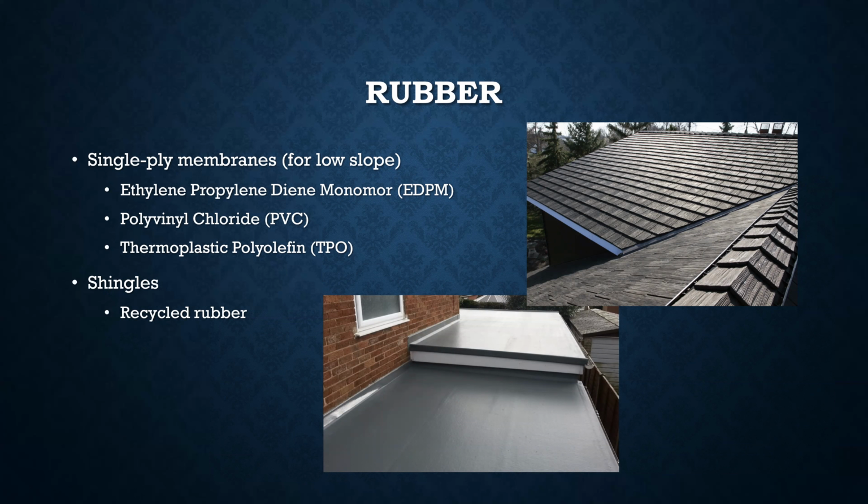There's some super cool advantages to rubber. It's a little more expensive to get on here because it is less frequently used. Therefore, labor is going to be harder to find, and the materials themselves are going to be a little more expensive, but you get to claim that you're recycling unrecyclable rubber, and they actually do stand up pretty well to abuse. The rubber material, just out of the fact that it's rubber, is going to have things bounce off a whole lot more than damage the rubber shingles themselves. So they're just very, very tough.